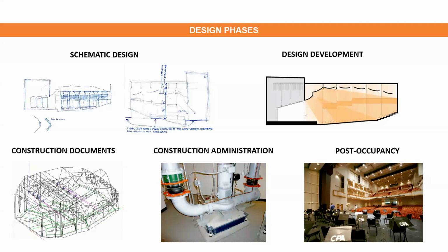So when we're looking at schematic design, when we have napkin sketches on paper, and then as the design develops, refining some of the acoustic concepts, and going into construction documents, looking at things like specifications for acoustic products and reviews of all the details, where all the junctures of two or more planes come together is very important. Also looking at CA services, whether it's coming out and doing site observations or measurements, and looking at post-occupancy to ensure that the acoustic criteria are being met.